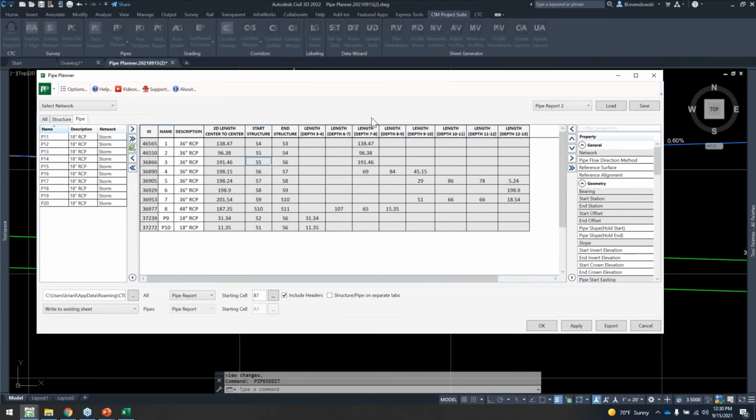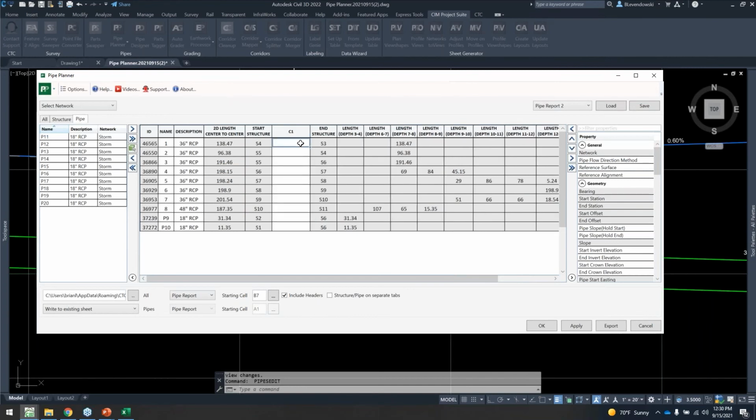So another question came in: is there a property option for pipe capacity and pipe velocity? If we could see them all in one place, we can make changes to the pipe right away without a design sheet. I don't want to show it in detail here, but things like pipe velocity and capacity can certainly be calculated right in here. We can insert columns in here. We can generate formulas, okay? So our flow calculations and velocity calculations can be done right in here.